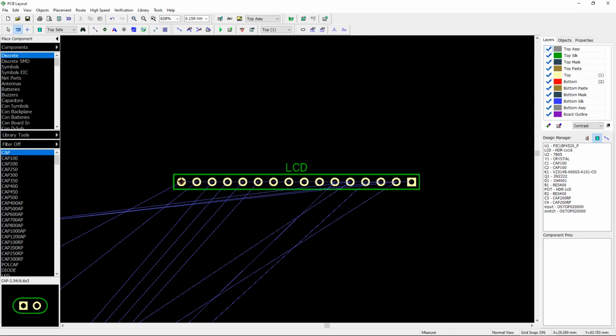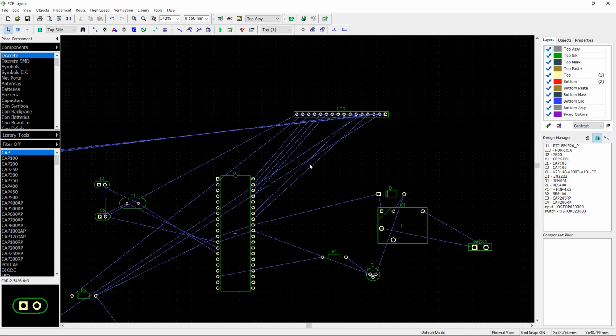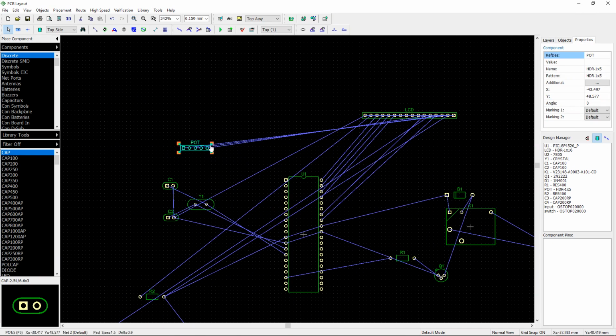You select on the center of the pin, then you go to the center of the next pin, right there, and the length is reflected 2.54 millimeters, which is the standard distance between the pins of a breadboard, which also is the standard of many of the components which you use, the LCD, the pins of the microcontrollers, the potentiometers, like in this case the potentiometer which I'm using.